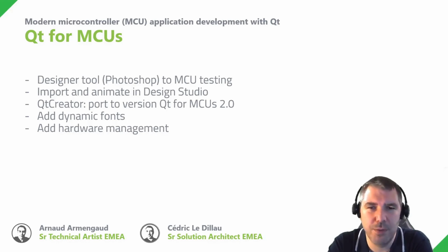I mean, simple hardware with IOs, with PWM. What function is in the SOC, in this system on chip, and not the high-end stacks like TCP/IP or USB. So for a simple project, it's totally doable without modifying the Qt for MCU libraries or the porting interface.